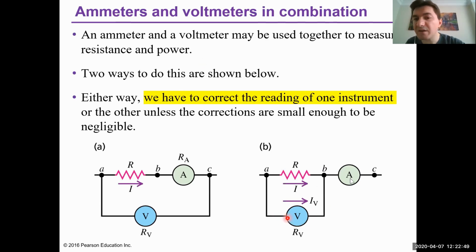That's nice, but what about the ammeter? The ammeter measures the current coming from the resistor, but there will also be another current passing through the voltmeter, and you will measure here the total current coming from that direction and that direction. In ideal voltmeters, the resistance of the voltmeter must be infinitely large. We discussed this during the last lecture, right? But it is not so in real cases. For this reason, a very small amount of current can also pass through the voltmeter, then the ammeter will read both of them, okay? You must be very careful.